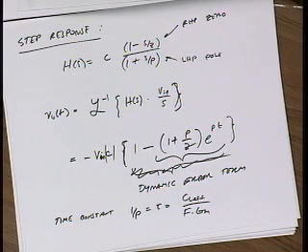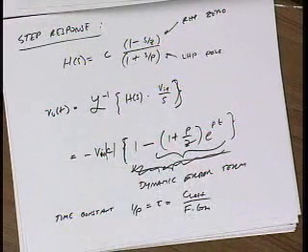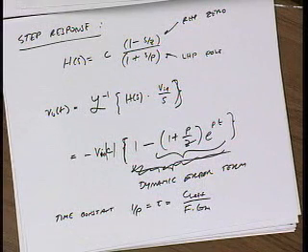Okay. The slewing rate of an op-amp. Okay, that's very good. How many guys studied slewing in 140? Okay, we'll talk about that probably next lecture. But yeah, there are nonlinear effects, right? This is a linear model. The linear model predicts that you have infinite bandwidth. I'm going to stick with my linear model. I'm going to say, look, I'm going to make sure my signals are small enough so that slewing doesn't happen. And you'll see that that's possible next lecture, so that my linear model is still valid. Do I get infinite bandwidth out?